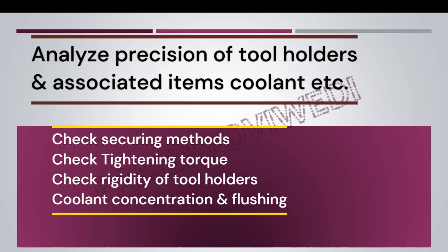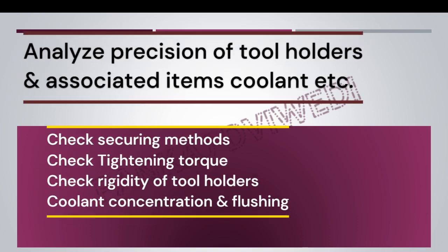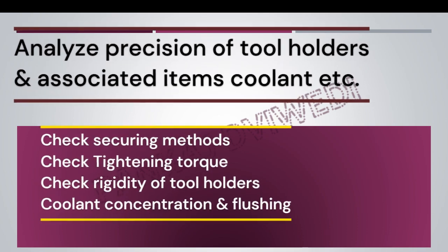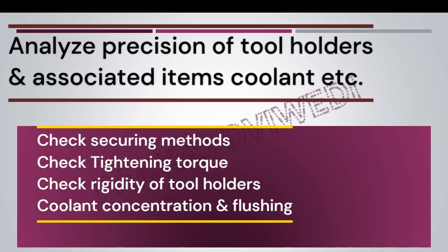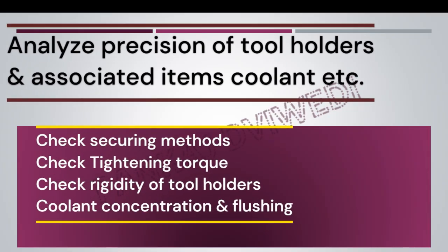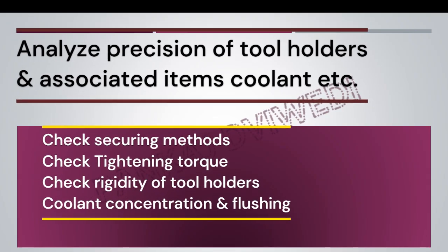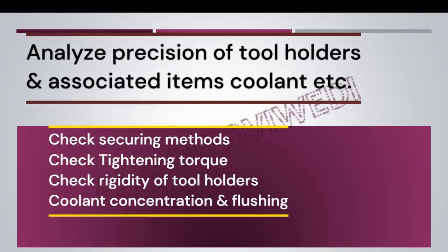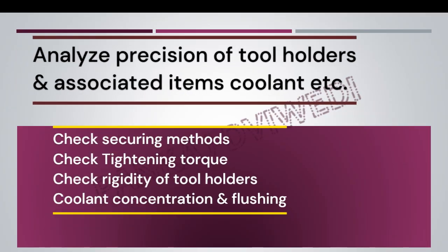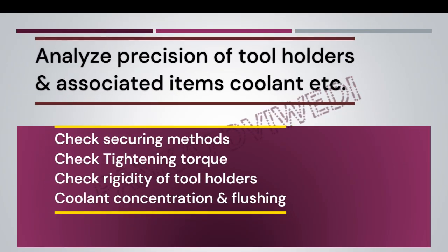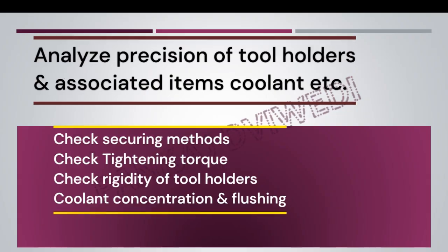While cutting, what kind of force is coming on the insert? See the rigidity of the tool holder, see the coolant flushing, coolant concentration, and flushing out of the chip breaker. So note down all these points.